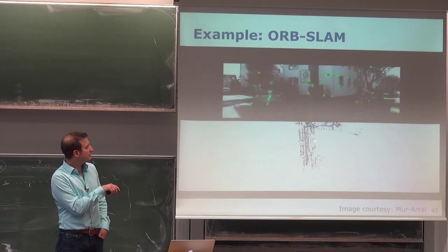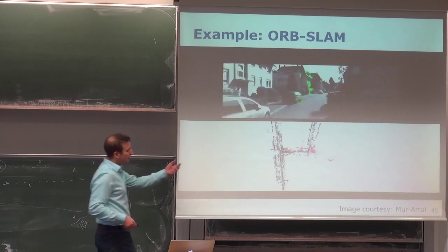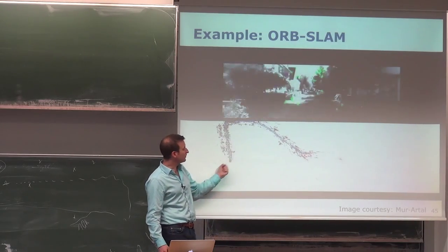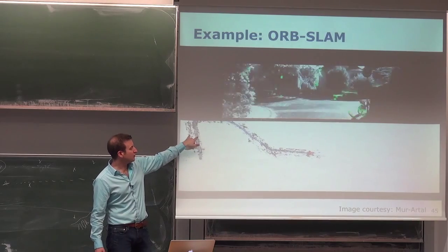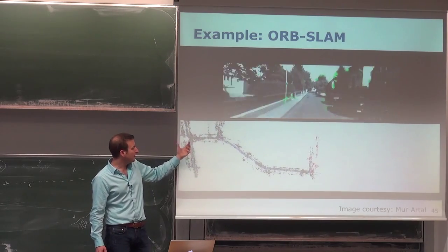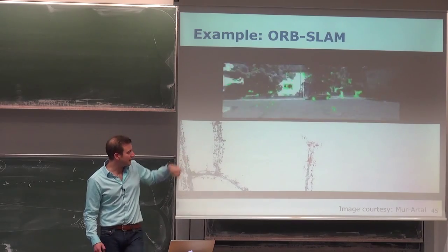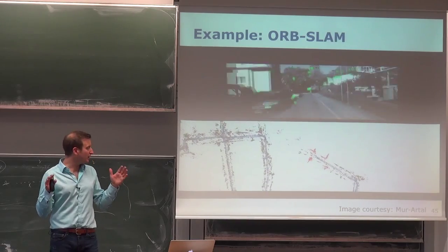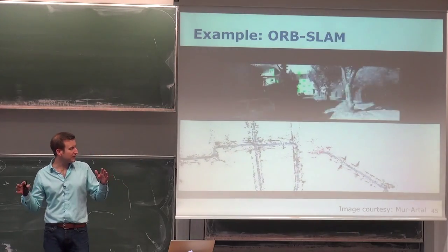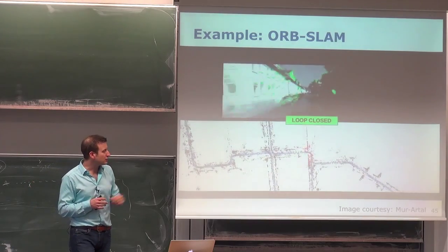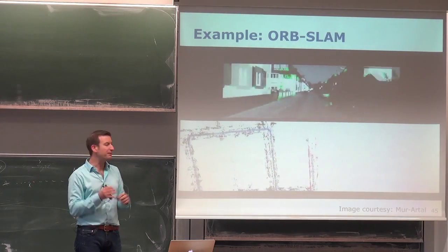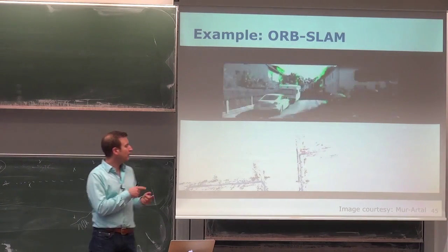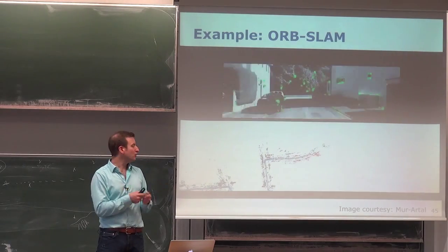What is important here is that you get a mismatch between the trajectory estimates. At some point in time, the system waits a little bit until it can make a good data association, not just between one image but between a sequence of images, and then can make the correct data association between those points and integrate it into the map. You saw this correction of the map, labeled as loop closure, which comes from the least squares approach, executed after every frame or nearly every frame, providing a correction of the map. Here you can see it again. The map snapped back because you get new observations relating the current observation with observations you obtained previously, which allows you to do these corrections.